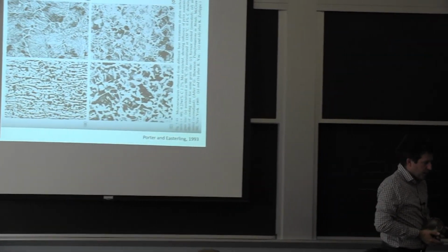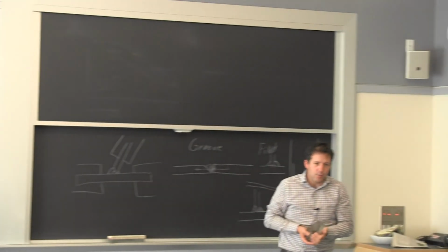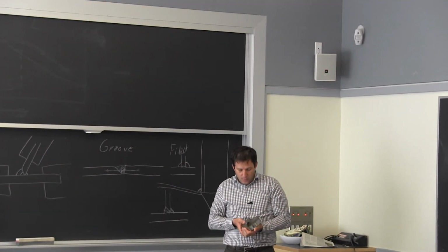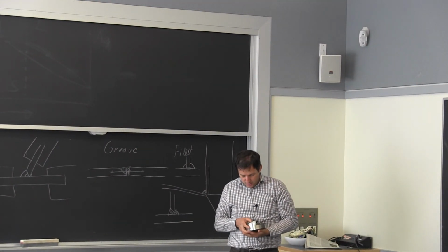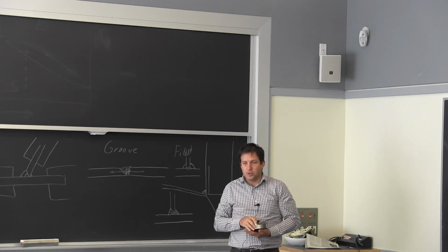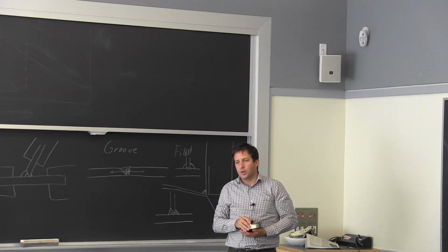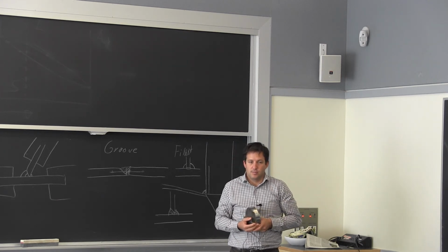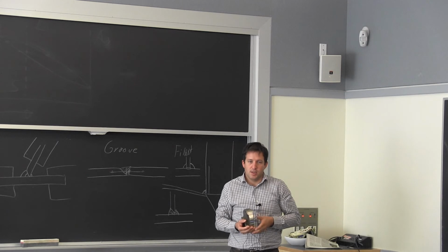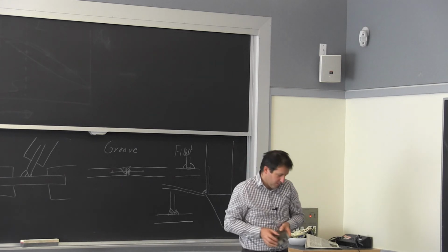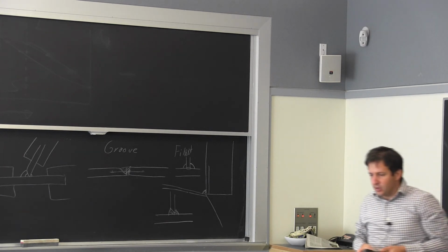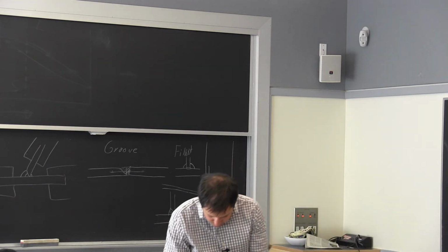But a lot of times, because this is already fairly heavy, you will want to go through the entire process of, hopefully you have enough alloying element here, to oil quench it as opposed to water quench it. Because if I water quench something this big, I get a lot of distortion. And then I may need to go back and machine it, and that's very, very expensive and difficult.